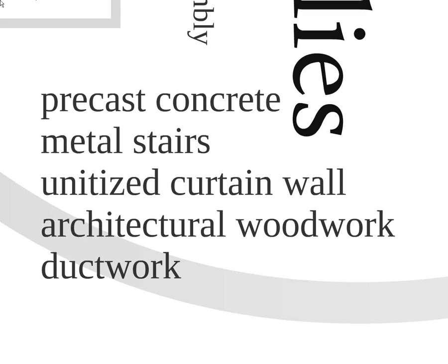Thank you. Some examples of this category are on your screen here, and of course precast concrete is totally custom. There's no standard sizes. Now metal stairs, of course, are assembled from standard bits and pieces, treads and risers, but again they have to be custom fabricated to meet the specific floor-to-floor heights and width of the stairs that are necessary. Unitized curtain wall, where there is some shop assembly, is another example of this, and of course architectural woodwork.